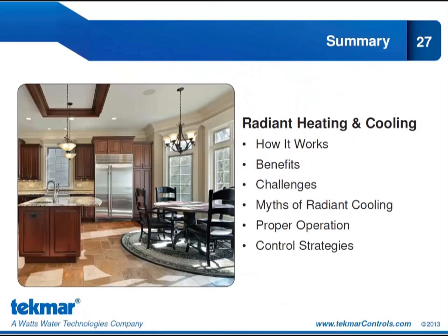And we'll talk about these more later in the presentation when we dive into the control points of the Tecmar controls 406 and 557. And lastly, in this module, we looked at some control strategies. Really the big ones here are the humidity control and the dew point reset. So the control strategy has got to have those points, or the radiant cooling system will disappoint the homeowner.